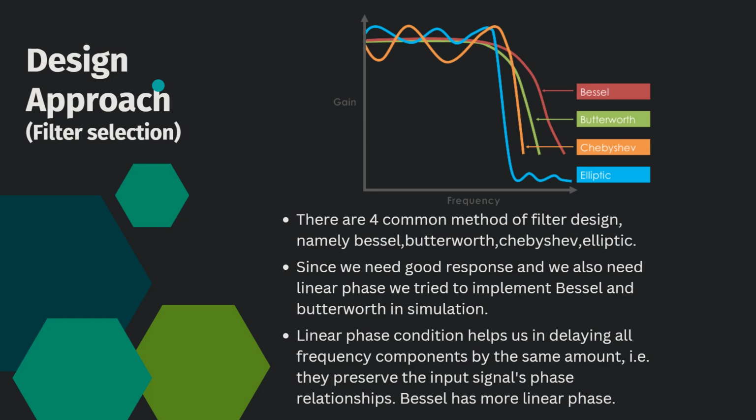So these are the plots for the different bandpass filters, and as we know we made two filters in the simulation, namely Butterworth and Bessel. We need to compare them. So these are for the comparison. As we see here, the red line indicates the second order and the green line indicates the third order. Based on the order, the steepness is decreasing.